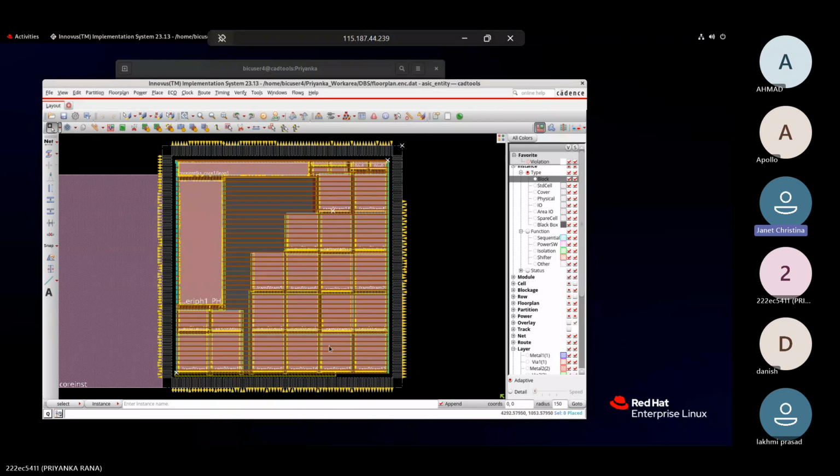Still why this issue? Now, if you see in the manual, there are no stripes running on the macros. Yes, open the manual. So that's how our stripes should be. Once this is done, the power plan is done. Ma'am, so like selecting each and every macro, we have to add those rings and then we have to add these stripes.